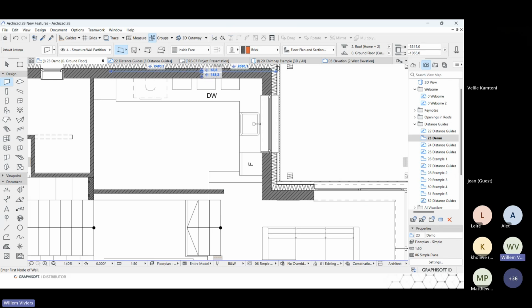They also speed up your workflow in the possibility of changing the length of walls or even beams. So when I select the wall, you'll note that I'm able to manipulate this value, and it will obviously update and change the geometry, in this case, the length of the wall.